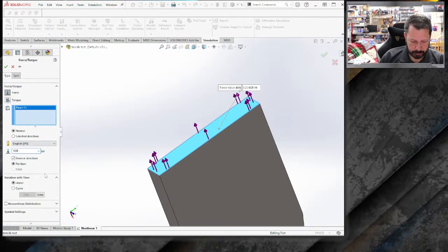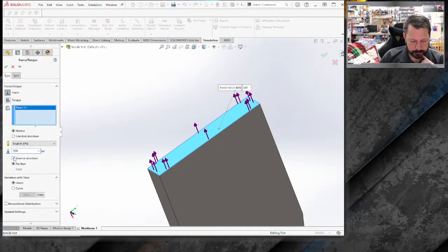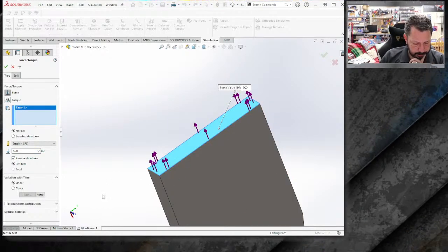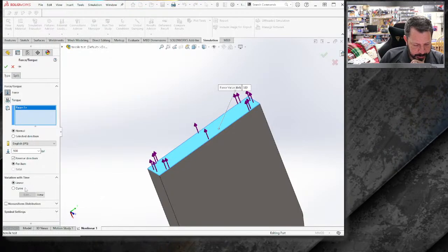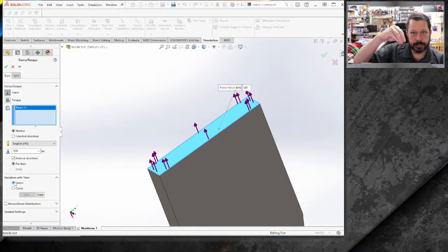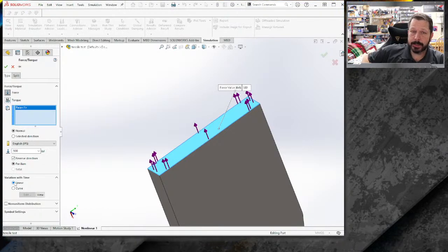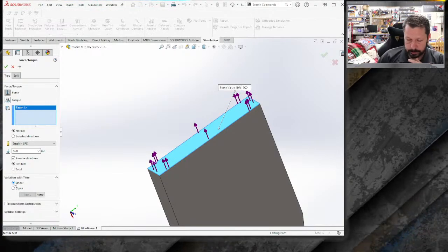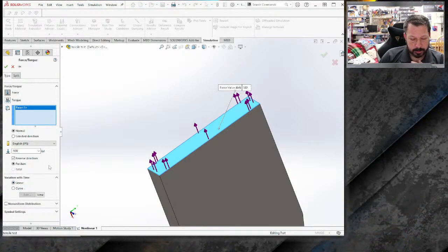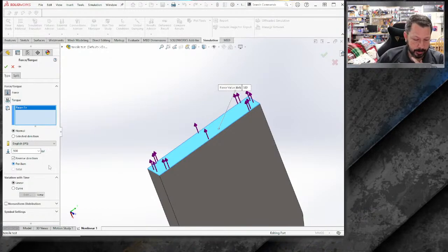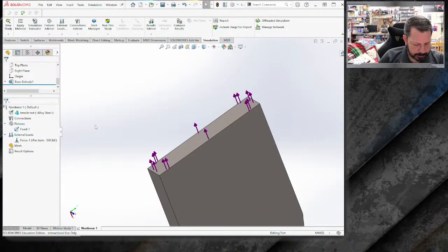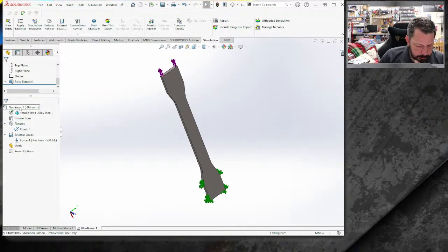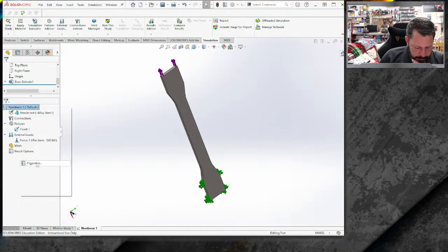And I've got it going the right way now. If it's pointing the other way, you click the reverse direction so that it goes the way you want it to go. I want it to pull it apart, so we'll do that. We will keep the force linear. That's really not how that happens. Again, you're applying a displacement that's linear, and the force actually is non-linear, remember our curve is not straight the whole time. But we'll try this because this is simpler to do as far as setting it up, and we'll see what happens. Let's right click on non-linear and look at our properties here.